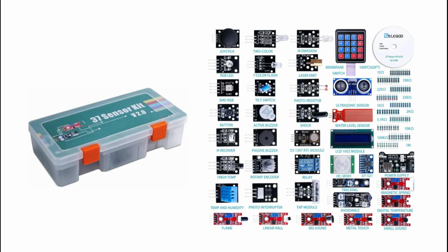The implementation for this that seemed to make the most sense involved the use of a motion or PIR sensor, a light-dependent resistor to check the lighting conditions, and then I'd use a push button to allow the user to test the lights, as well as the charge level of the battery, which would be displayed via an LCD screen. The button, as well as the appropriate motion and light signals, would then send a high signal from the Arduino to one side of a relay, with the other side connected to the lights.